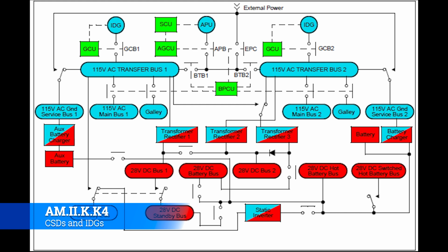It really is something to see once you see how well thought out it is, how intricate it actually is, and then how simple it is. It doesn't take a whole lot of super duper computers or anything like that. Even though all those GCUs are computers, you don't necessarily need them to make the aircraft work. It's taking DC power and AC power, and inverting and transforming it as needed. That way, any one power source should be able to power the whole plane, which is pretty cool.